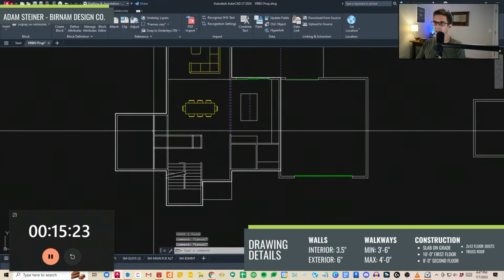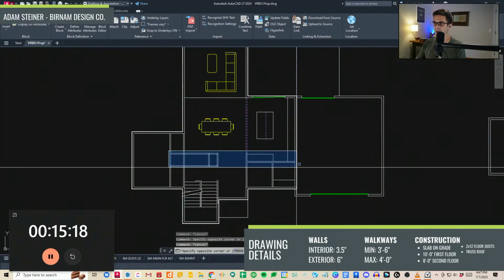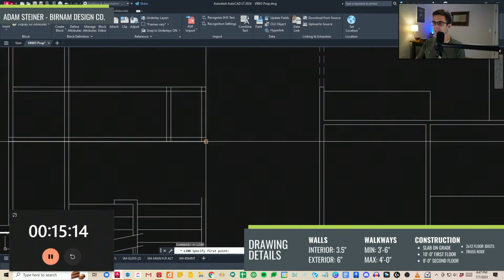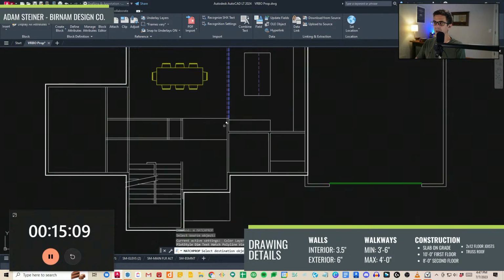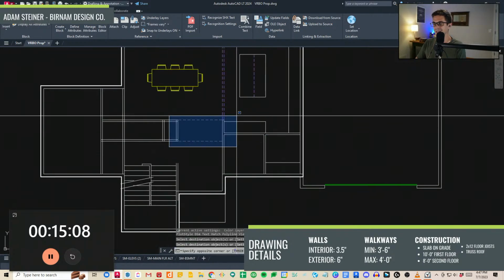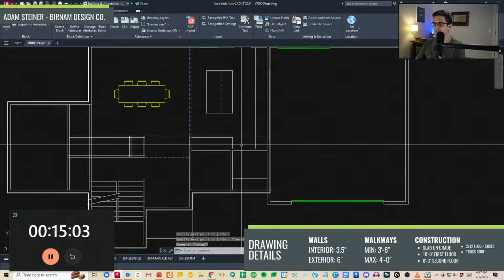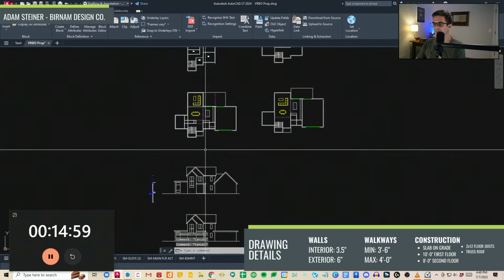Well, actually, we can just fur down this area. Just gonna run a trunk here and run something through there. So we might have to drop the ceiling just here, but it's actually really concise. Mechanically, if you're slab on grade, you could just drop the ceiling through there, and it looks intentionally, you know, architecturally designed, and not just like an afterthought.